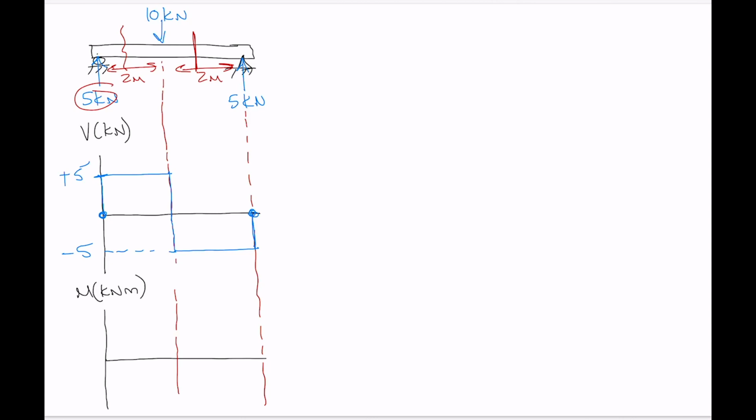We know we've done everything properly. We started at 0, we've arrived back at 0. Good, that means that we've done things properly. So it's a nice little check for ourselves there. So some shading, and then the shear diagram's done, right? Easy, easy, easy. Okay, let's do the moment diagram. Moment diagram starts at 0, ends at 0. Good.